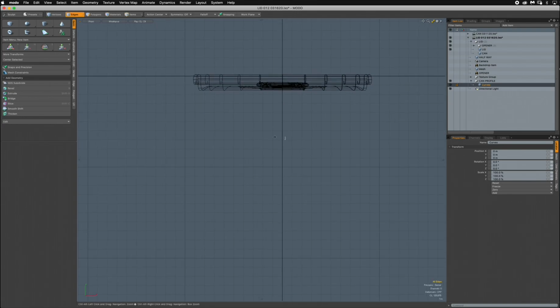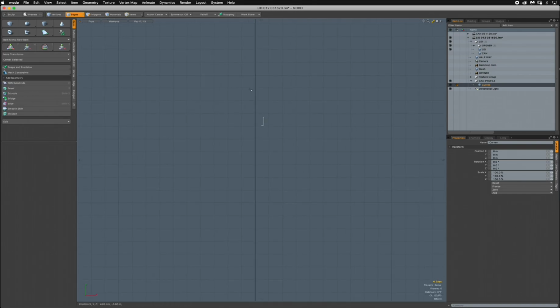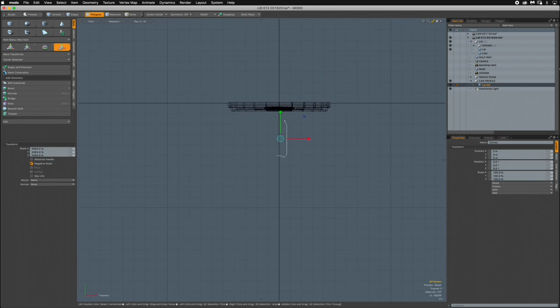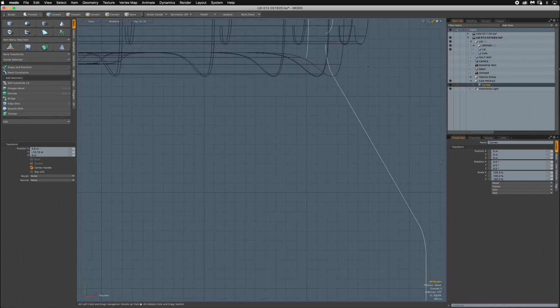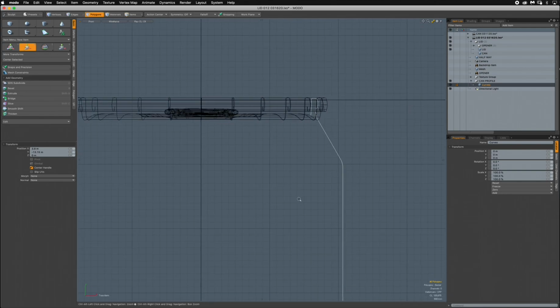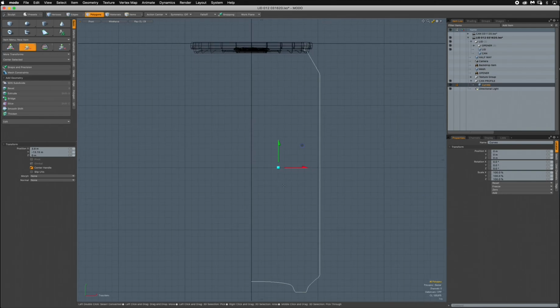And what we're doing is we're going to scale this so that it matches the size of this can here. So let's just select polygon, R for scale, and just drag. And this part in the bottom is going to tell you the thickness of the can. So when you align it, it's got to feel like it's inside of here. So it needs a little bit more.